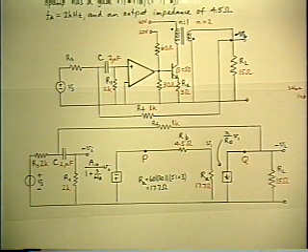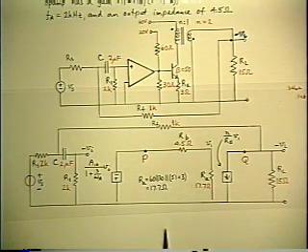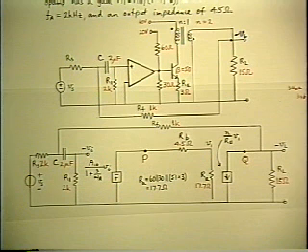Notice again, I've attempted to adopt the basic principle. Before you start doing any analysis and writing equations, make sure you strip down the model so you don't keep anything in it that isn't going to be relevant in the answer. Okay, now we have a linearized model. The loop is closed. Now we want to choose a suitable injection point. Already we'll take into account the fact we're not going to break it. We're going to use the equivalent technique of injecting the test signal. So where can we inject the test signal?